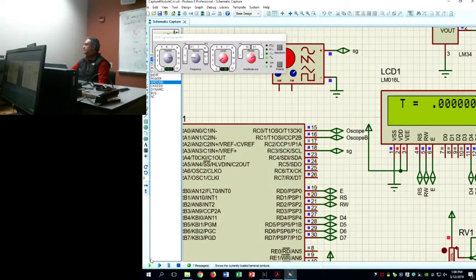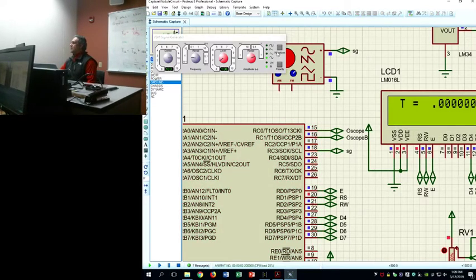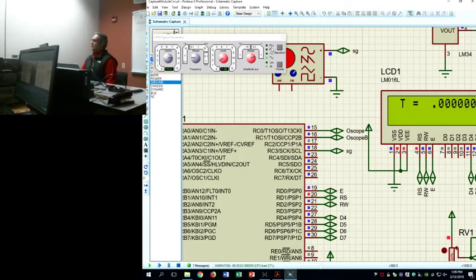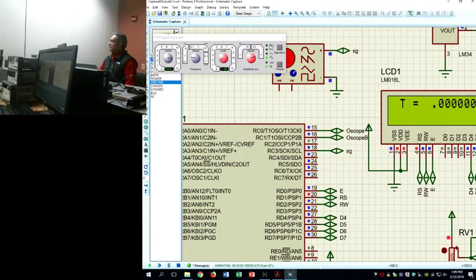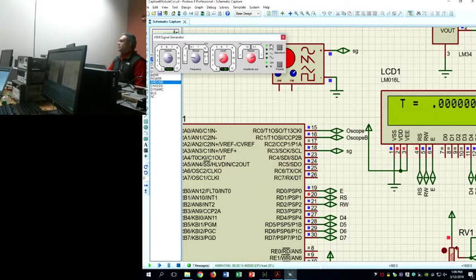All right, and then we got to make sure that we get this right. If you notice here on the right side, I want to make sure that you have this in square wave mode. And instead of bipolar, you want this unipolar. So this is unipolar square wave. And then I want to make sure that I got 5 volts.